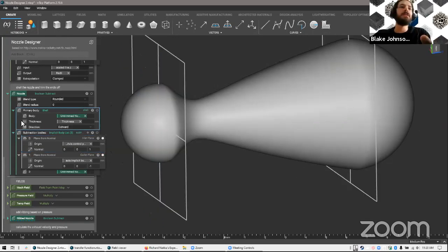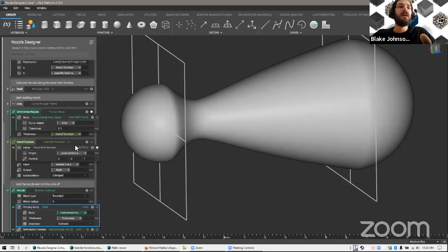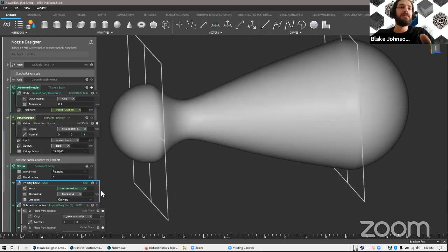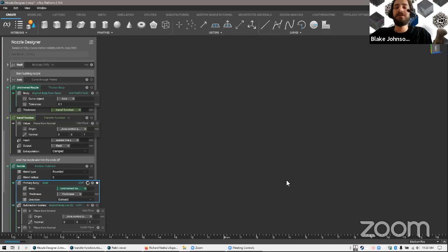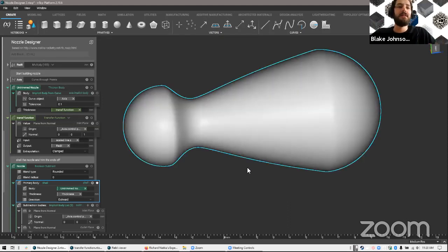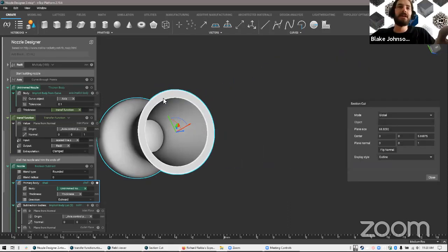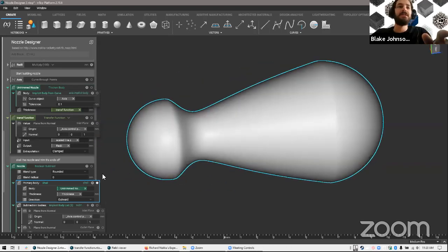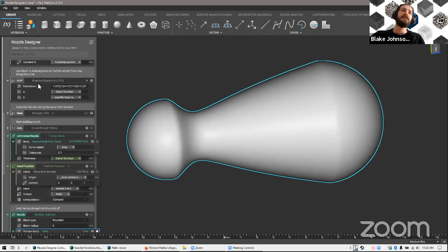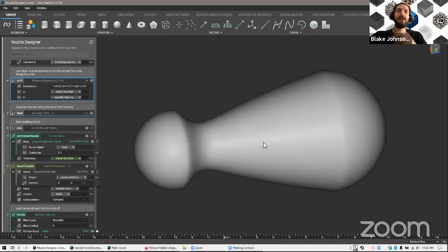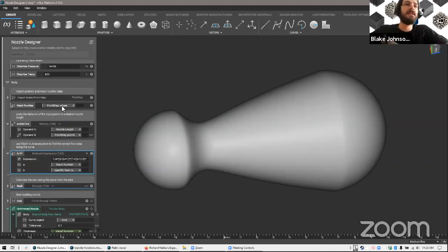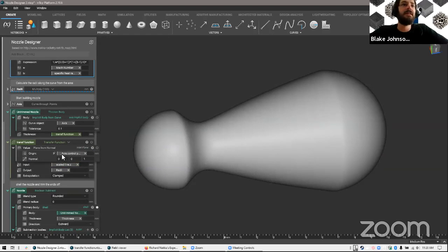And another step we do in this block is to shell the shape. So if we look at this, it shouldn't look any different because we're shelling. But if we do a cross section, we see we've actually created a shell. Another important thing is I used an outward shelling because that maintains the exact cross-sectional area that we have from this shape. So it's taking this and shelling outward from it, which allows us to maintain that cross-sectional area for the flow.